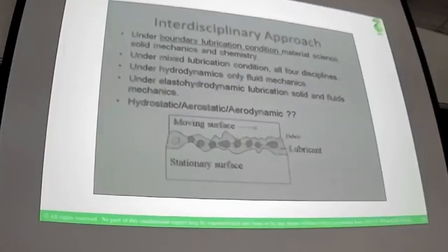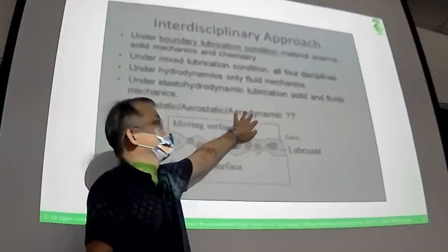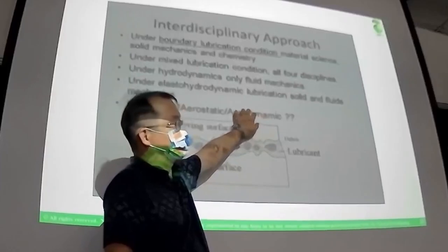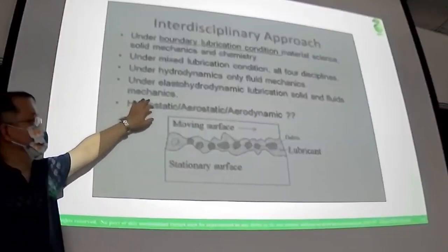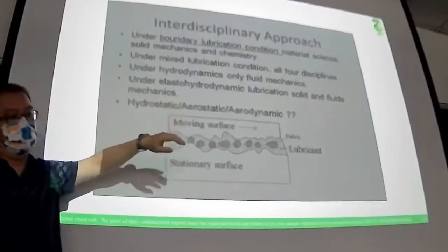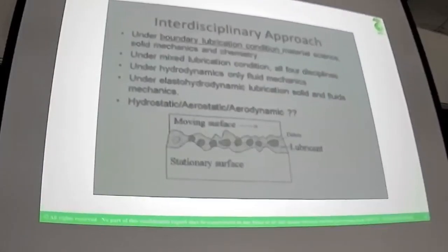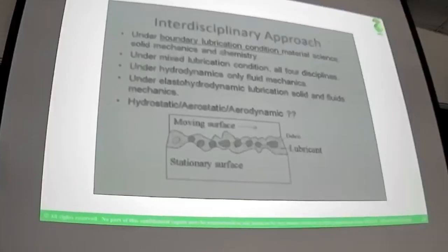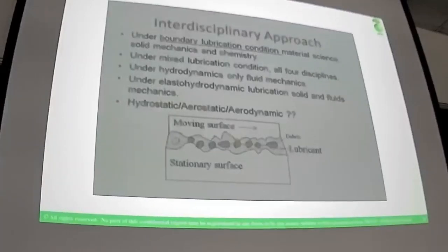And aerodynamic or hydrodynamic bearings are rarely applied in mechanical applications. Usually it is hydrostatic and aerostatic bearings, because the surfaces are separated, the film thickness is thick enough, and without any physical contact you have an extremely low coefficient of friction.